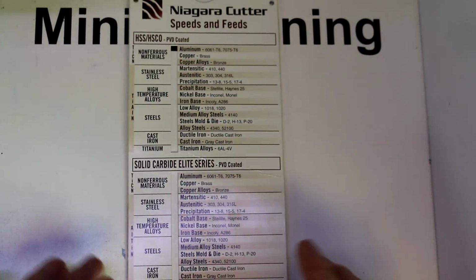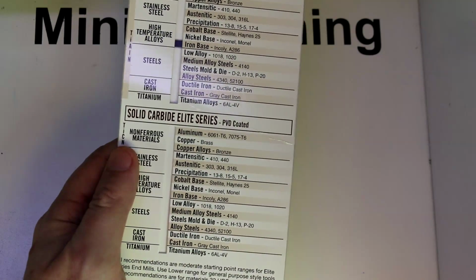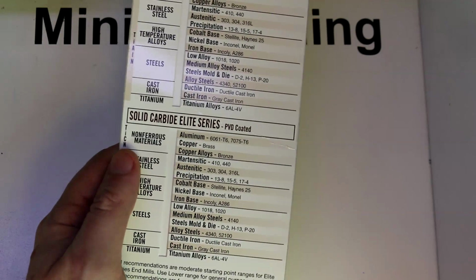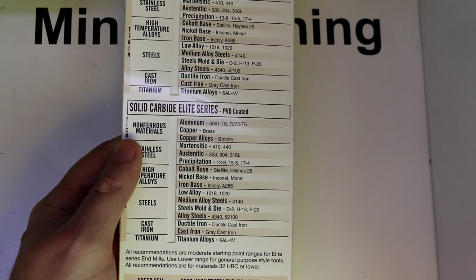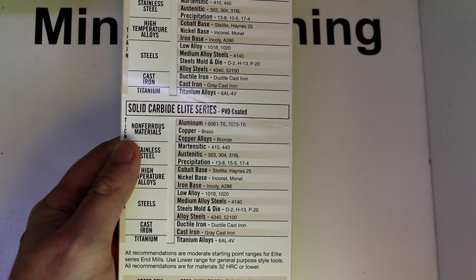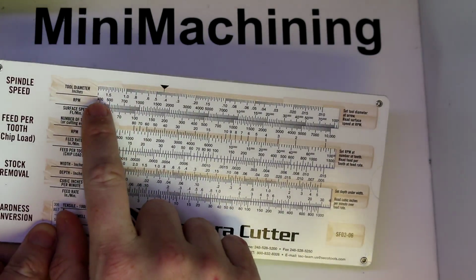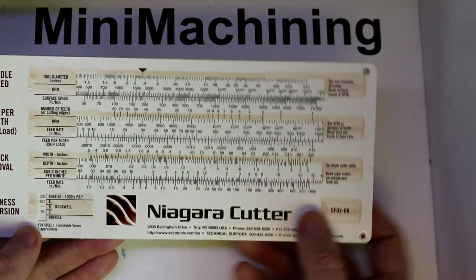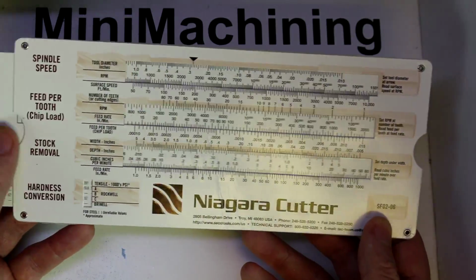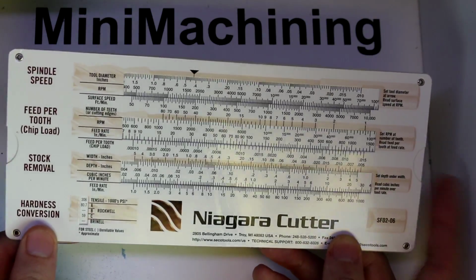There are elite series from this manufacturer, and there are different areas here where we can move this up and down. So we've got a slide rule basically to look at what's the recommended surface feet per minute, as well as our feed rate, so inches per tooth, depending on the end mill diameter. And then on this side, we can take some of that information and calculate out our spindle speeds and how quickly we're going to be removing stock and all that good stuff. So there are a few manufacturers that still make these, but not very many. A lot of this has been replaced by computer programs.